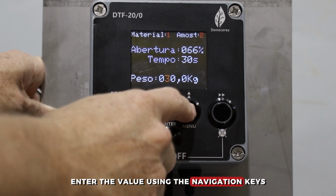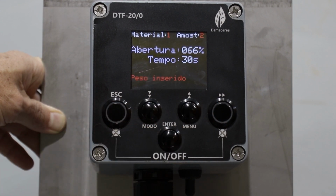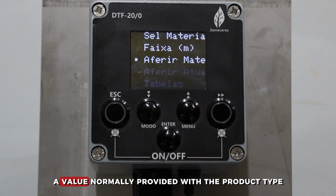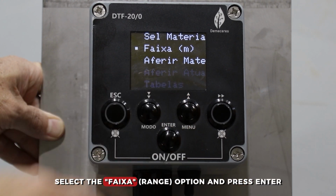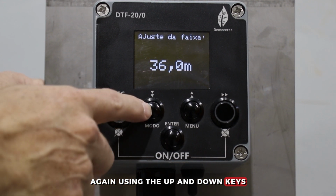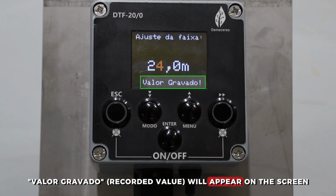Enter the value using the navigation keys and press the Enter key to confirm Peso inserido. Press Enter again to record the sample data. Once the 2 samples are finished, you must proceed to record the spreading range, a value normally provided with the product type. Using the up and down keys, select the Faixa and Metros option and press Enter. Again, using the up and down keys, enter the recommended spreading range according to the product. Press Enter to confirm. The message Valor Gravado will appear on the screen.